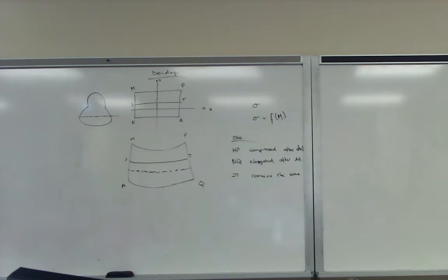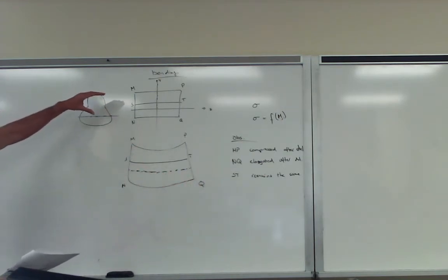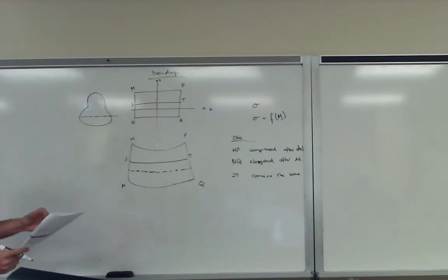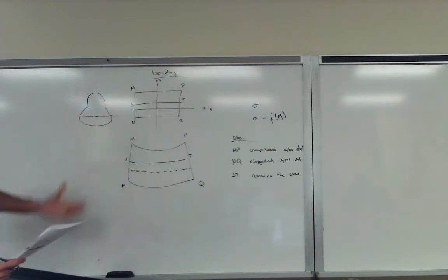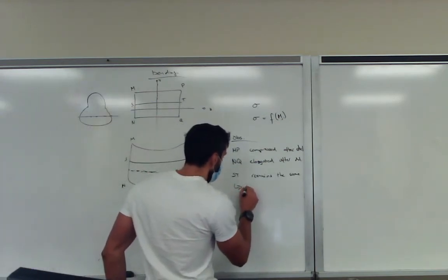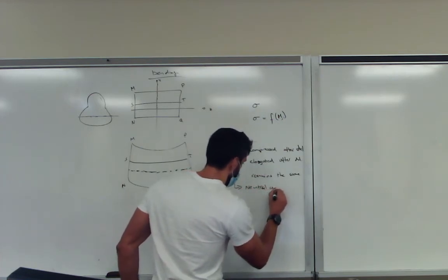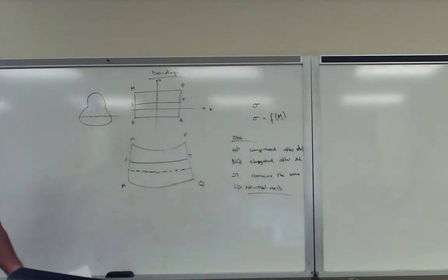And the latter observation is important because this means that during the deformation, we can define an axis system that always remains the same in the cross section. And that's a bit dependent also on the geometry. And this ST is known as your neutral axis. As the name says itself, it's neutral, so it remains the same pre and post deformation.